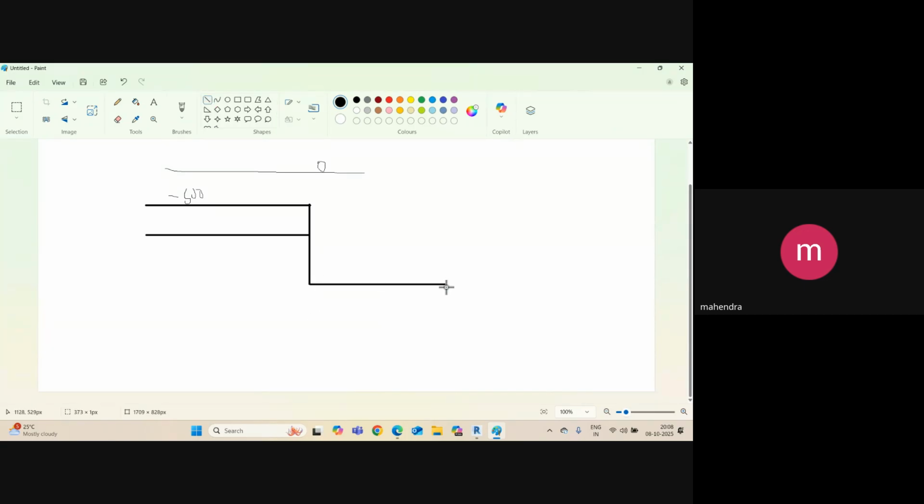And this is, suppose, minus 1.5, which means 1500. So the total will be 2 meter from ground. And this gap from here to here, the difference is 1.5 meter, and you need to add this type of footing, a sloped or step footing.